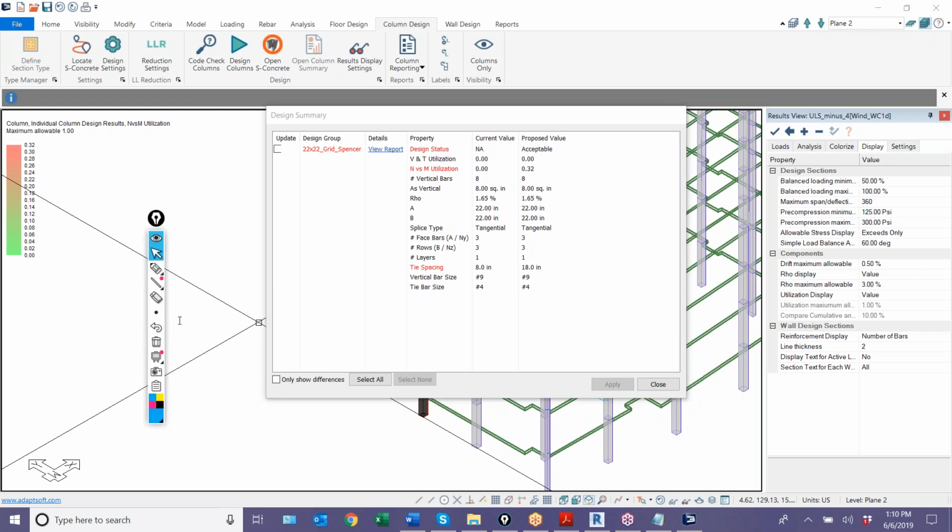The check considers the reinforcement. It has to. The reinforcement is considered in terms of strain compatibility for the code check. The program will produce an interaction based on what rebar is there, and that means that the program must consider the reinforcement in the section.